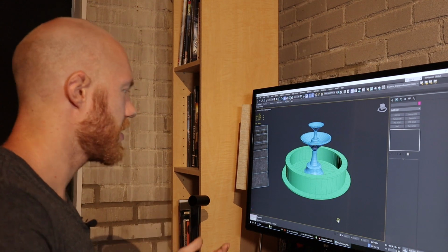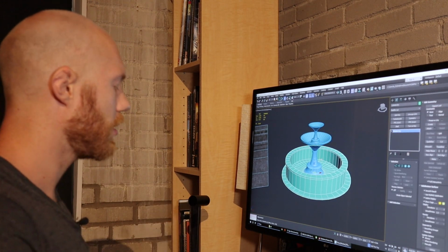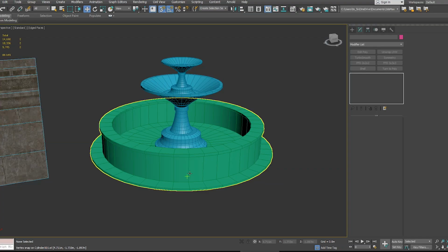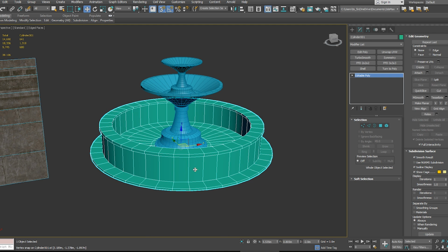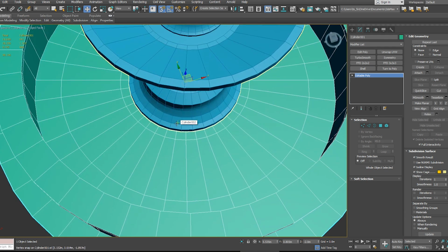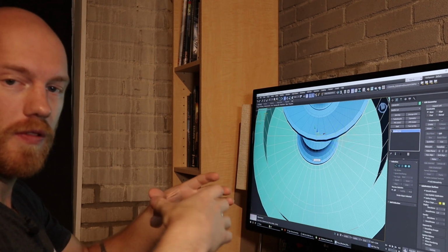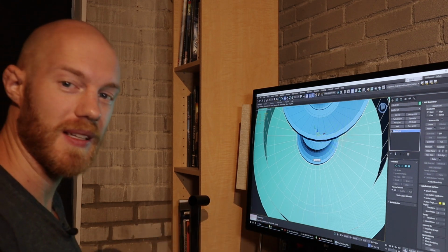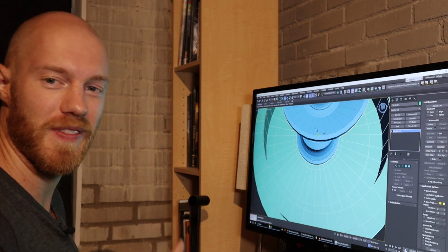Also in our scene, I've created this very basic fountain model, because a lot of you guys had questions about dealing with cylindrical shapes. Not so much the vertical sides of the fountain. I think most of you realize you can probably just quickly give that a cylindrical UVW map, and that'll give you a nice clean strip on any vertical rounded shapes. But a lot of the questions pertain to stuff like these inner top caps, because if you were to give that a planar map, your UVs would basically be a big circle, and trying to get that adjusted into a clean strip, for most people, it's like, how do I do that? It's a bit of a nightmare.